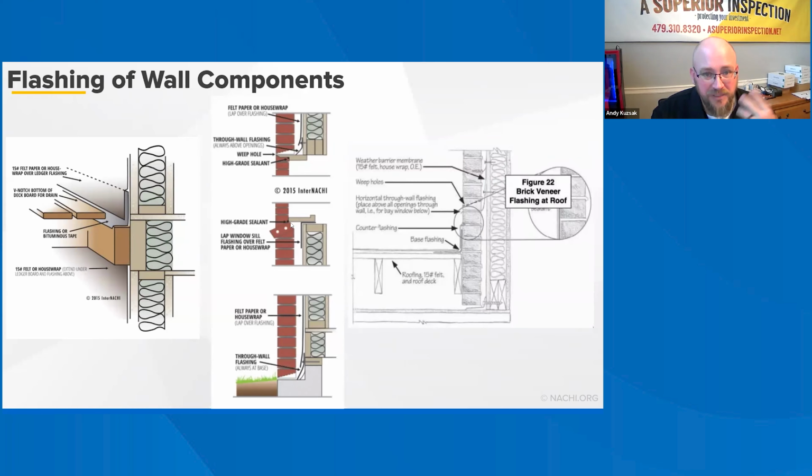Because a lot of times on new construction, the wood is not completely dried in. Over the course of the first year of the home, the wood does completely dry, and the wood framing of this wall will shrink just a little bit. And because the brick is attached to the structural sheathing, it pulls the brick down and subsequently will tilt the brick back to the inside.